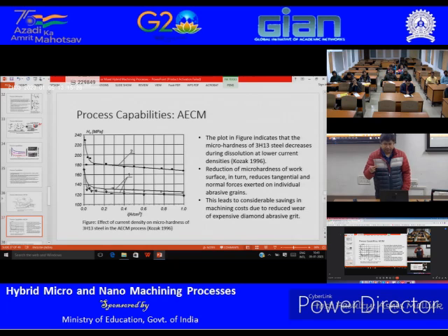And that can put higher cutting forces on those abrasive particles. On the other hand, for ECM, the electrochemical dissolution is happening, and there is probably very minimal to no recast layer, so the material is comparatively softer there. Okay, so that's the benefit of the abrasive assisted ECM process over the abrasive assisted EDM process.